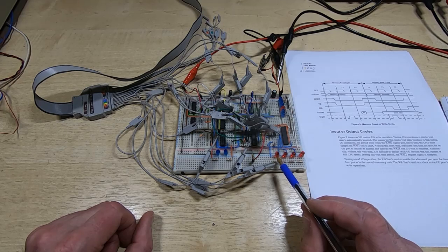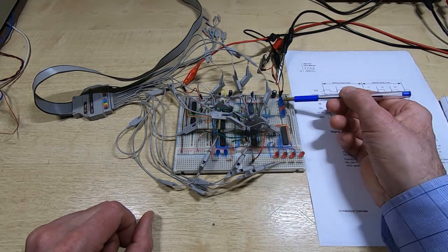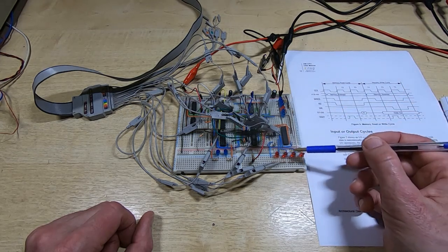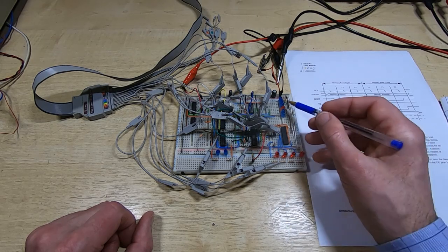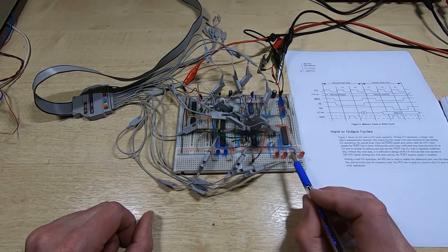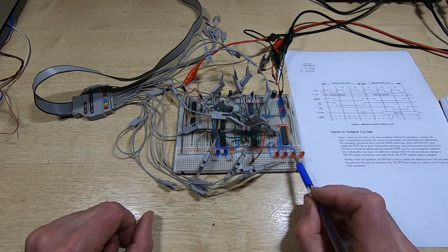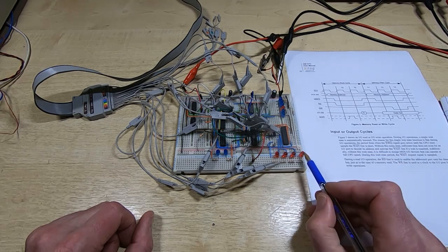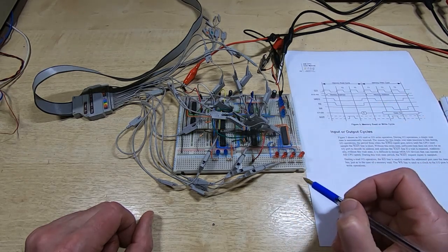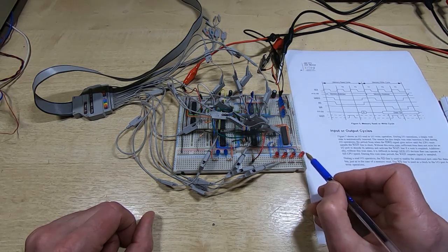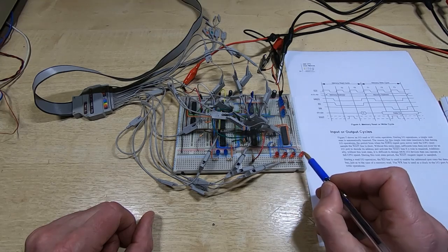So on the left we have the write. Now don't forget, these are the read and write going to the floppy drive controller device, and these are the read and write that go through to the Z80. So they're not the same thing. So we have the write signal on the left here, the read signal, the in-out. Although we're not using the in-out directly, we still have to control it to make sure it's not left floating. Otherwise we could end up with data going to the wrong part of the system when we try and write to RAM. And then we have the memory request line on the right.